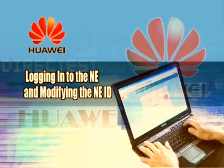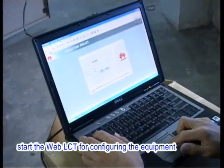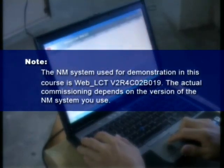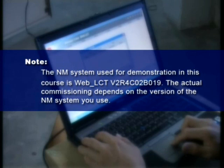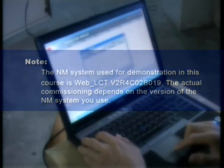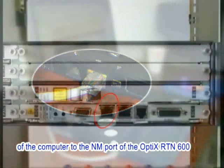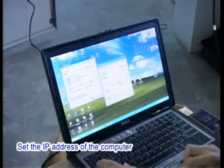2. Logging into the NE and modifying the NE ID. After the equipment is normally started, start the Web LCT for configuring the equipment. Note: the LMT system used for demonstration in this course is Web LCT V2R4C02B019. The actual commissioning depends on the version of the NMS you use. Use a network cable to connect the network port of the computer to the NM port of the OptiX RTN 600. Set the IP address of the computer.